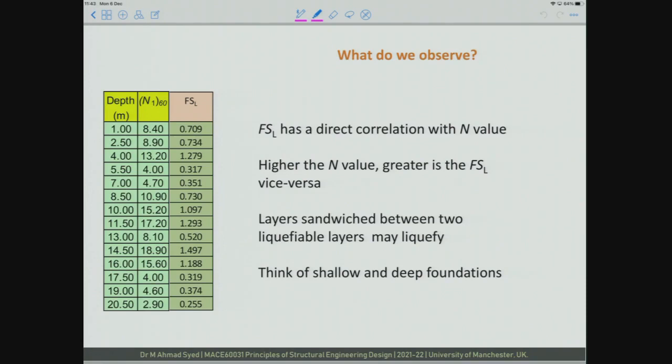artificially. If you look at the definition of liquefaction, it means that the soil is loose, so densify it beforehand rather than wait for the earthquake to densify it and risk liquefaction at this site. So you may need to take some ground engineering measures for that. If you are going deeper into the ground, then perhaps a simple option could be that you ignore this depth, for example, so there is no skin friction for this depth.